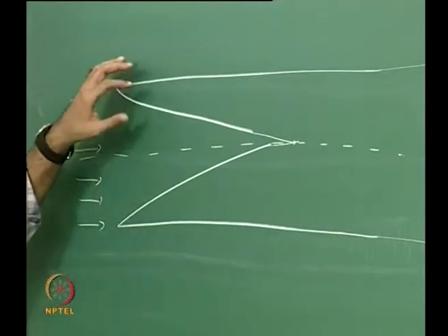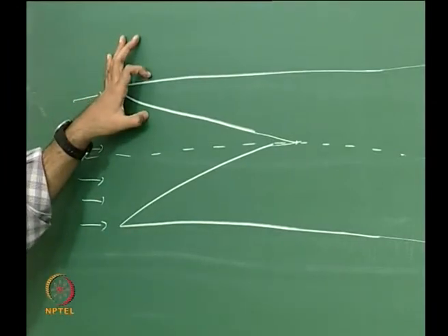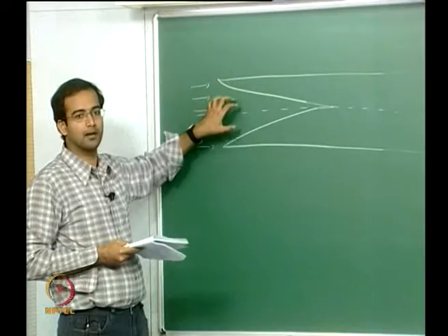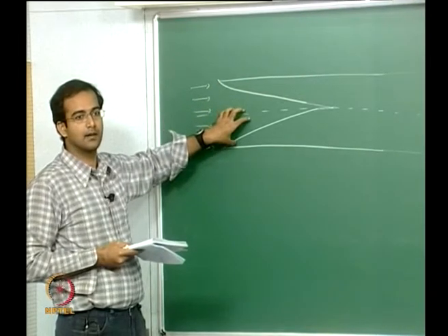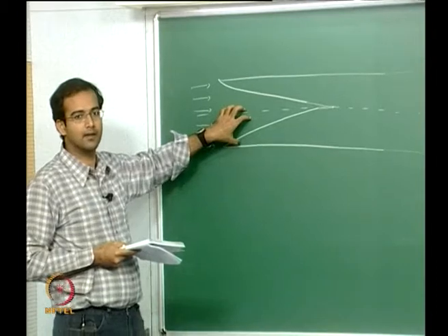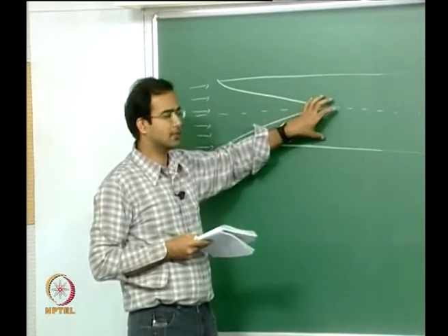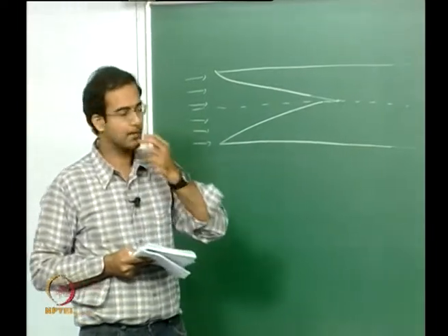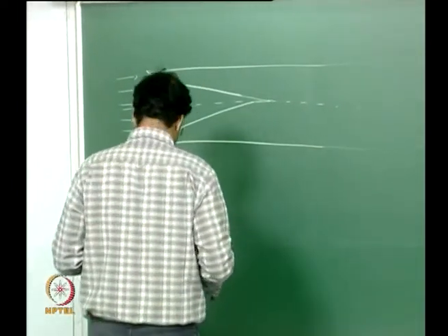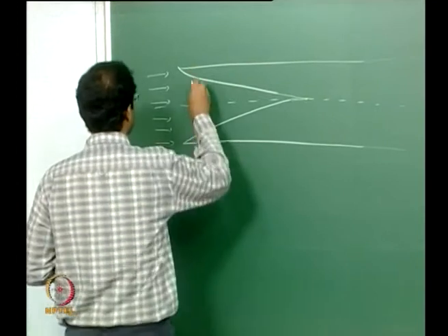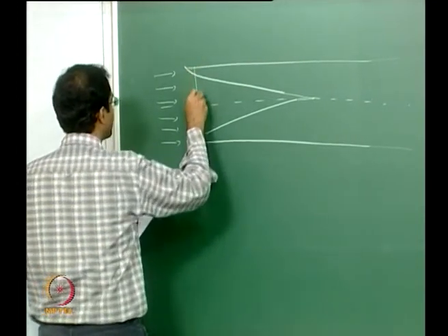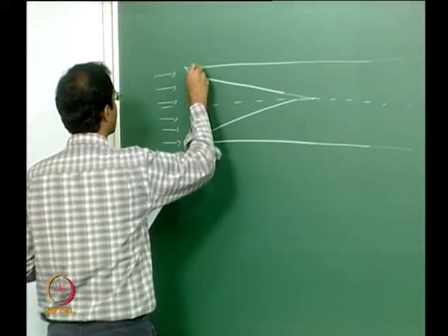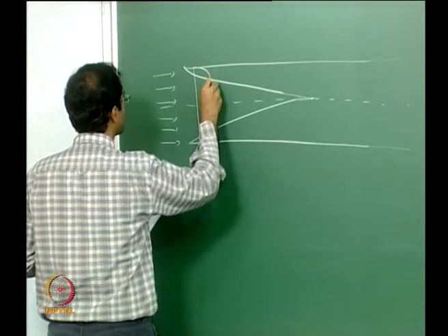At the inlet you have a very small region close to the plates where viscous effects are important, and outside, potential inviscid flow theory is still valid, whereas once the two boundary layers merge, everything is viscous dominated. Now if you look at how the profiles are drawn, somewhere at the inlet you can have a profile something like this.